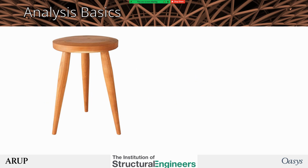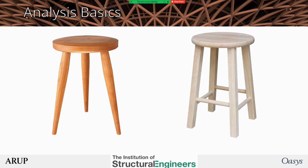To illustrate this, let's consider the stool paradox. Now, if you sit centrally on a three-legged stool, then your weight will be carried, approximately, equally down each leg. The design load on each leg is your weight divided by 3. But if you sit on a four-legged stool, then will the design load be divided by 4? No, because the stool will not be perfectly built, the floor it sits on won't be perfectly flat, and only 2, possibly 3 legs will actually be fully in contact with the floor. Your weight will be mostly carried by 2 of the legs, meaning that the design load is now your weight divided by 2, an increase of 50% thanks to the addition of an extra leg.